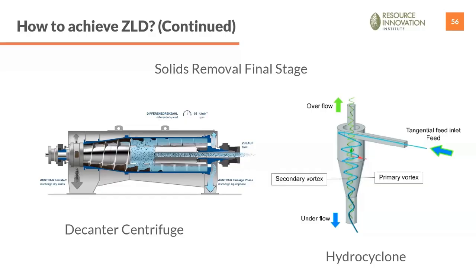processes, as the crystallizers tend to cake up the salts, making the physical removal of salts a chore or creating the need to include scrapers and other mechanical equipment to physically remove salts from inside a crystallizer. However, there are novel ways of dealing with salts, such as the use of oil as a transport medium at the time of evaporation, which prevents the salts from fouling up the equipment and from adhering to other surfaces. This oil then transports these precipitated salts, as they are no longer in suspension, since salts have a much lower solubility level in oil.